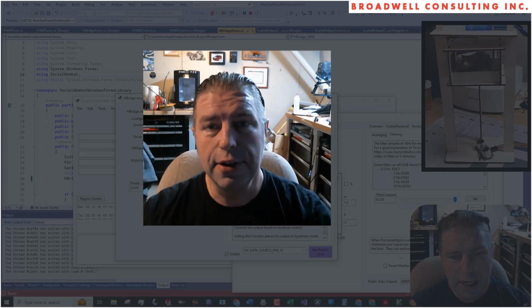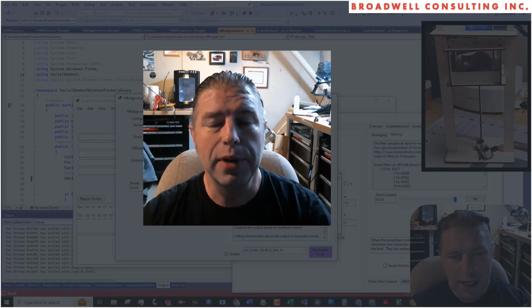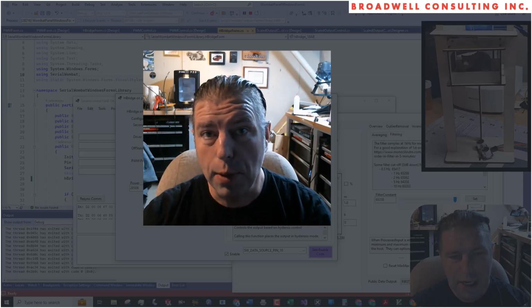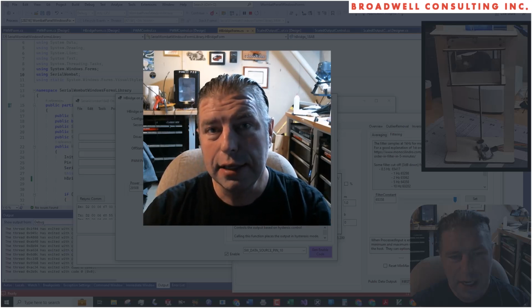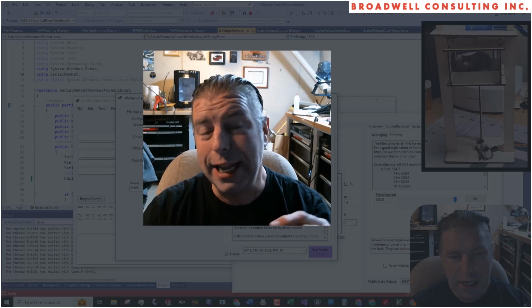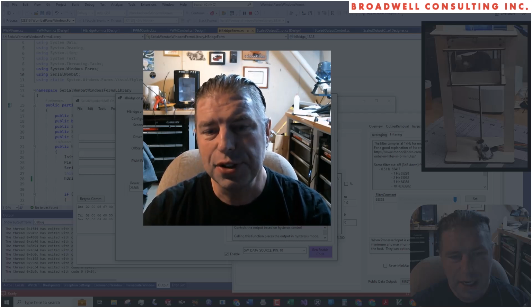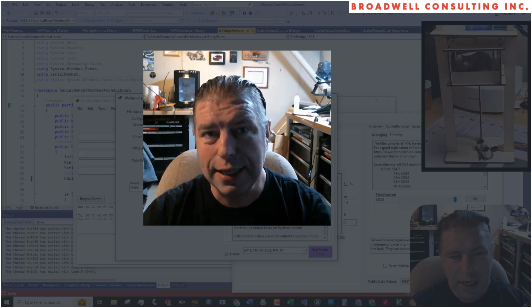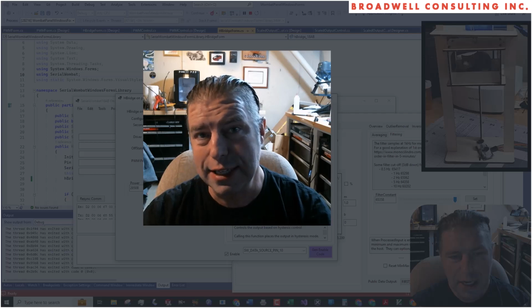Okay, let's stop the video for a second and talk about what happened, why it went all the way to the top. In retrospect, that filter was getting in our way on the input scaling on the ultrasonic distance sensor input. The problem was we're only moving across a range of about 80. And so the change in was only moving by a few counts per sample. And that was actually falling off of the end of the filter. It never added it up enough to move the filter. And so it appeared as if the ultrasonic sensor was frozen.